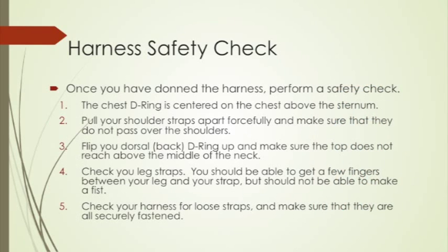Once you have on the safety harness, perform a safety check. This safety check should take place each time the harness is used. If there is an issue or concern with your harness, you should bring it to the attention of the competent person on your job site. It is always a good idea to review the manufacturer's owner's manual for safety checks that may be specific to your harness type.